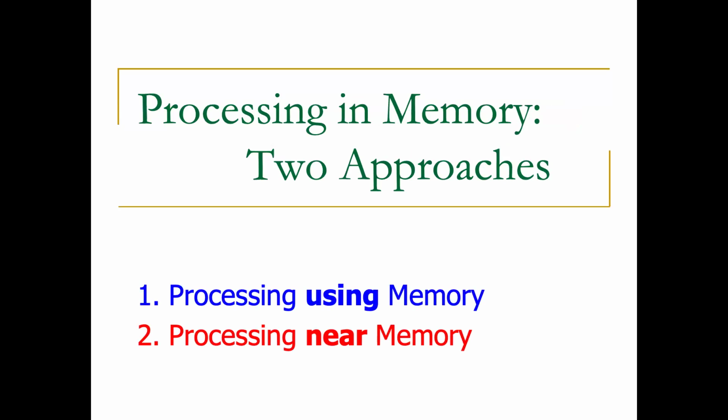So let's start with processing near memory. What does this mean? So you have a processor, logic, and you have memory, a memory device. Processing near memory says, put the logic closer, closer, closer, closer, and at some point integrate it in the memory device. It could be inside the memory device. It could be near the subarray, inside the subarray, in a 3D stacked logic layer, etc. But logic and memory are separate.